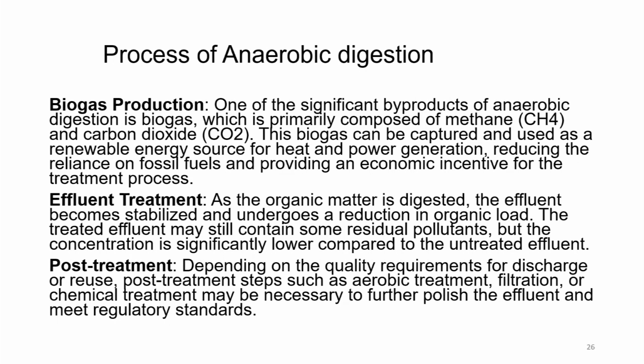Depending on the quality requirements for the discharge or reuse, post-treatment steps such as aerobic treatment, filtration or chemical treatment may be necessary to further polish the effluent and meet regulatory standards. So, it is possible that the effluent is further post-treated with chemical treatment or aerobic treatment or filtration, so that it matches with the regulatory standards.